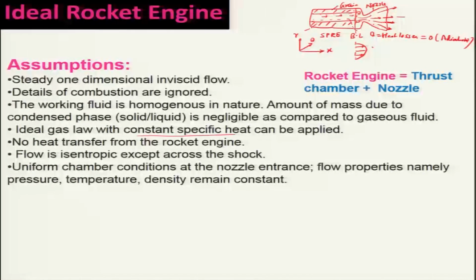But however, between the real one and the ideal one, what we will be assuming is a uniform velocity at the nozzle entrance and also at the exit. Here, if you look at the two dimensional flow, there will be an axial component and a radial component of velocity, but we are considering the flow to be uniform over this region.